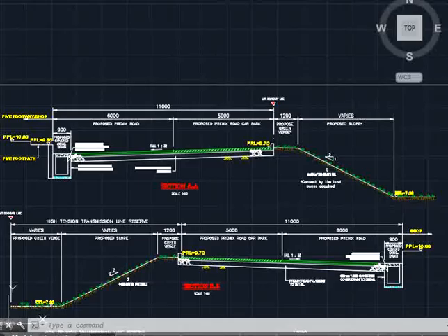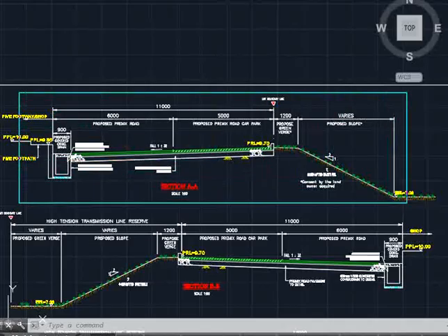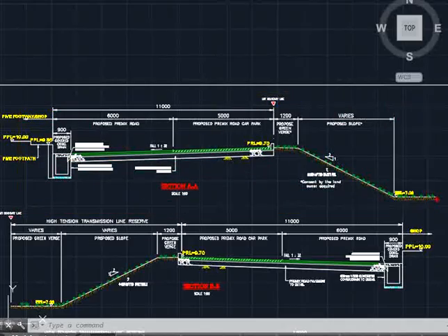As you can see from the example road section here, the existing earth level is relatively low as compared to the proposed road level. There will be a significant difference in terms of the elevations. This design deals with the slope with a gradient of 1 to 2 in the adjacent lot. This definitely will have to get the consent from the respective landowners.